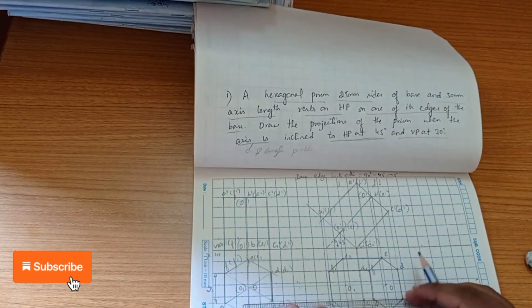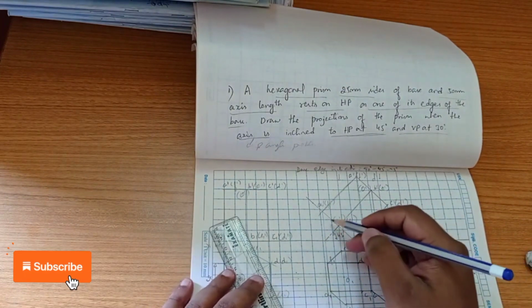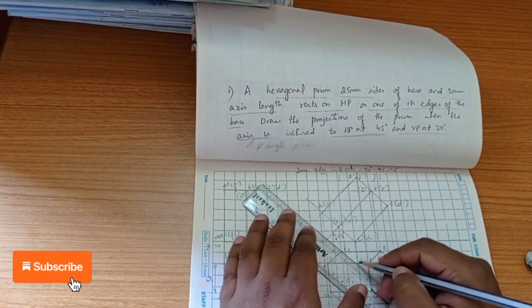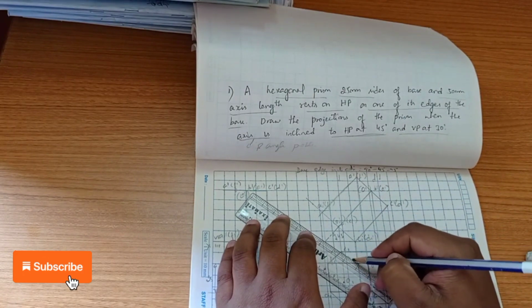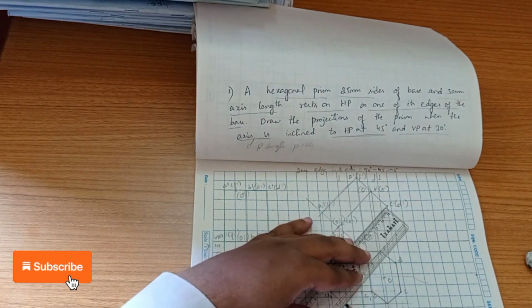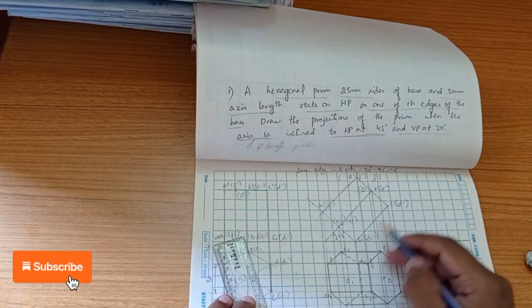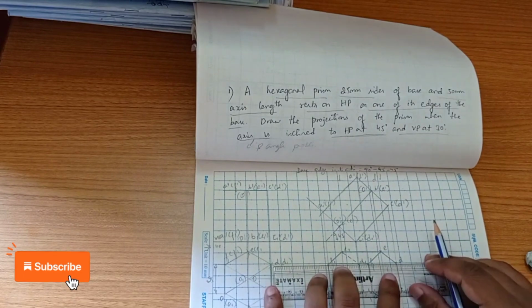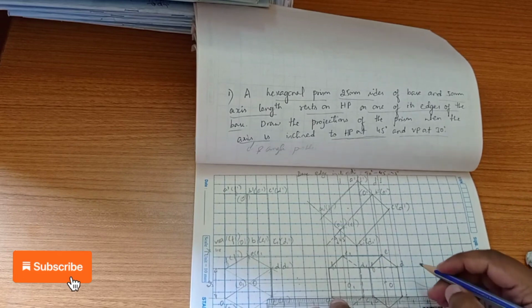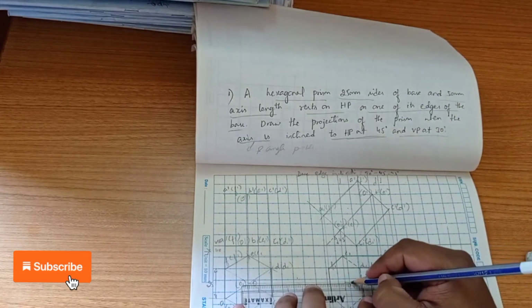F1 and A1 visible from the top view, but this base of the hexagon is not visible from the top view. So part of it is written with the dashed line. Okay, and then this rectangular face C dash, D dash and C1 dash, this rectangular face is also not visible, so we can show part of it here. Okay, and we can show an axis here, so this is an axis line.